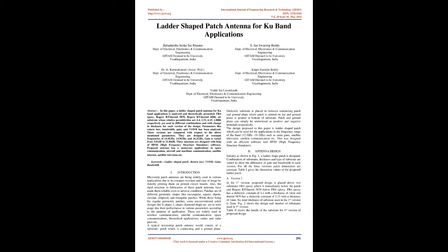FR4 epoxy, Rogers RT/duroid 5870, Rogers RT/duroid 6006, and an air substrate, whose relative permittivities are 4.4, 2.33, 6.15, and 1.0006 respectively, are used in different combinations and with change in thickness for each version of the design.